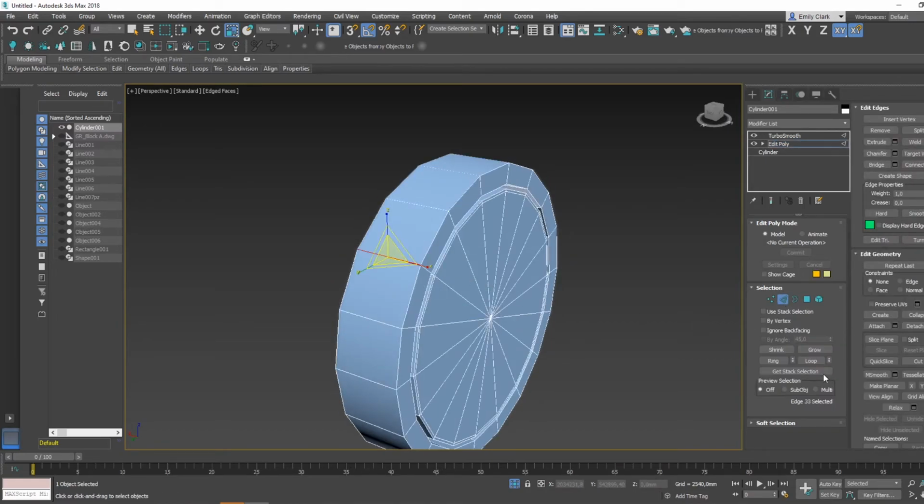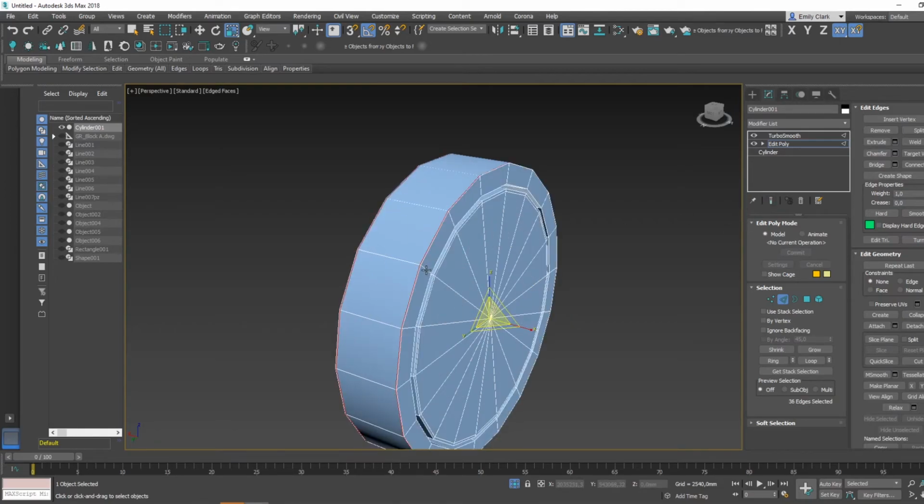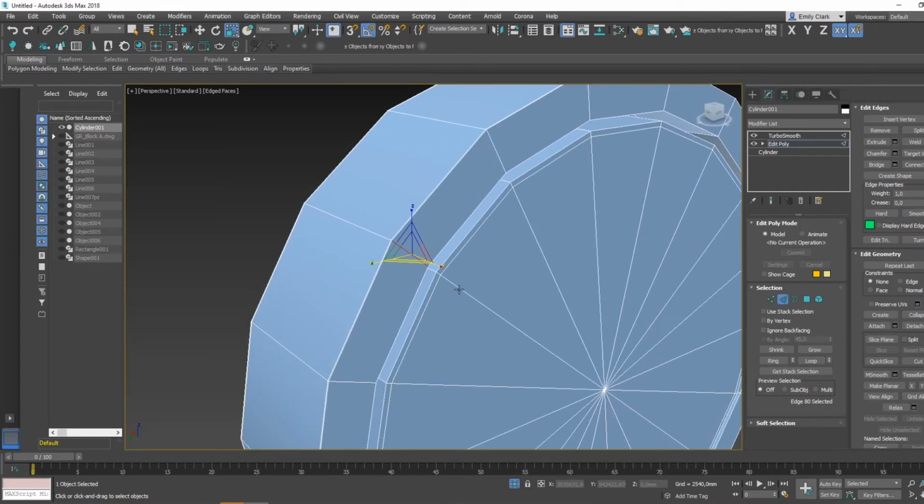We need to add some lines towards the edging of all the surfaces. So you can see here, if we turn that on, it gets smoother and more of a harder surface. So we'll just make that about 98. Just untick that. And we'll just go around doing the same for all the edges.